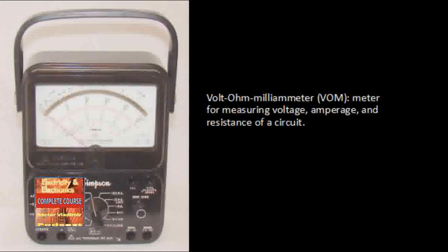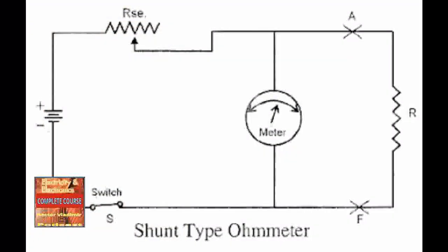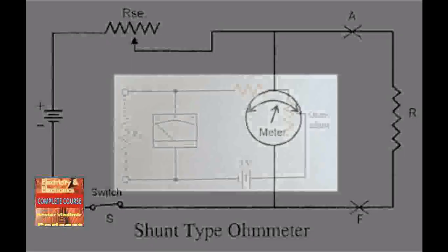Caution. Before connecting an ohm meter to an electrical circuit to read an unknown value, be sure that the circuit is not energized. An energized circuit will damage the meter and can be harmful to you. Electrical energy in a circuit is not needed to operate the meter movement coil, as it is when using the voltmeter or amp meter. The batteries inside the case provide the source of power for the ohm meter. Connecting the ohm meter to an energized circuit will apply the circuit's voltage directly to the coil and battery, which can result in damage to the meter and possible harm to you.